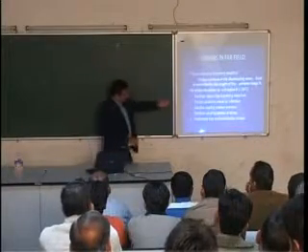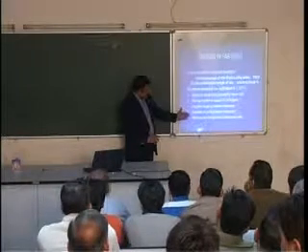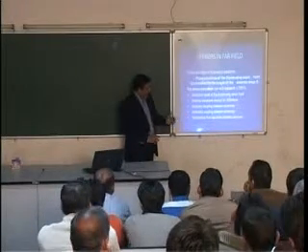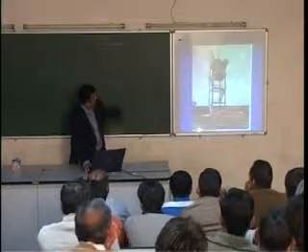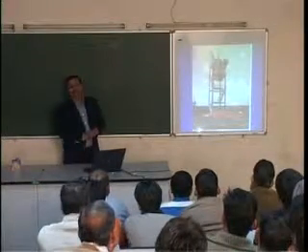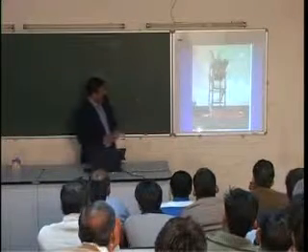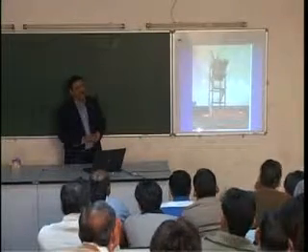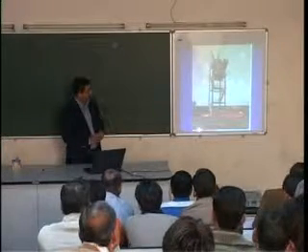Now another error which is there is the periodic variation called reflection, inductor coupling between antennas, radiation coupling between antennas, interference from a spurious radiating source. Now what is the alternative then? The alternative, so this is one tower. Earlier in our stack also we used to have this tower, and we used to keep an antenna on the top, and another tower is there on the transmitting side, and we are measuring the performance of the antenna.